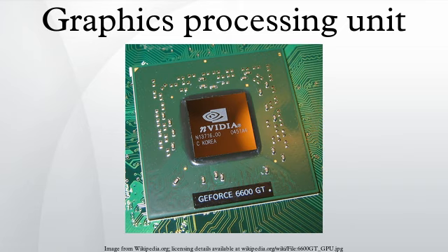History, 1980s. In 1983, Intel made the iSBX 275 video graphics controller multi-module board, for industrial systems based on the Multibus standard. The card was based on the ATI 2720 graphics display controller, and accelerated the drawing of lines, arcs, rectangles, and character bitmaps. The frame buffer was also accelerated through loading via DMA. The board was intended for use with Intel's line of Multibus industrial single-board computer plug-in cards.